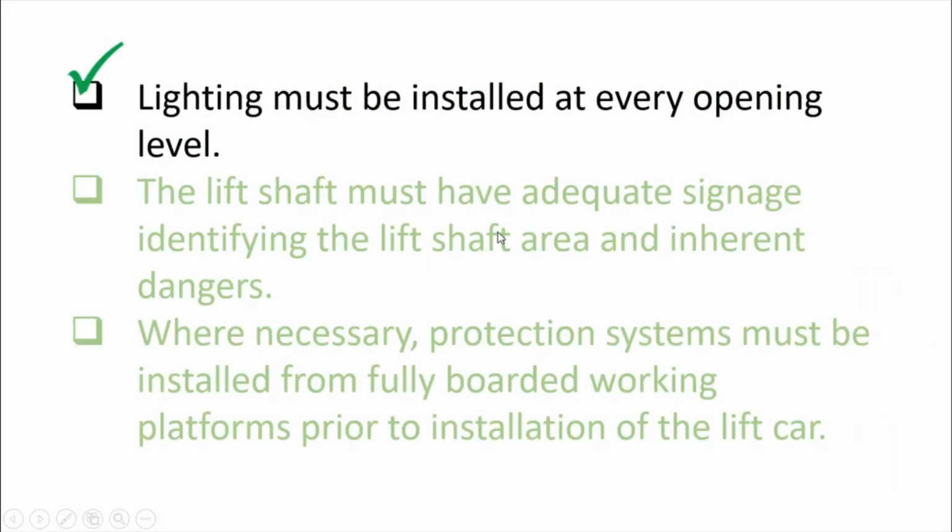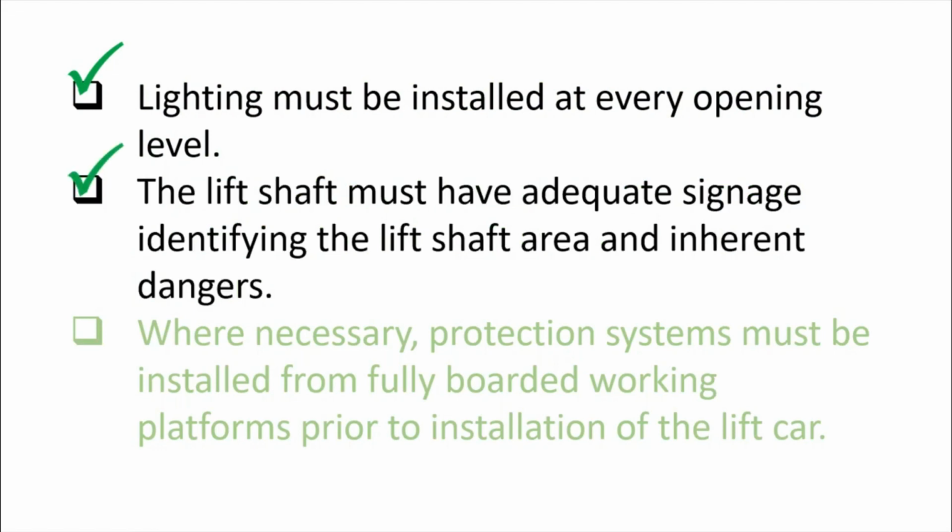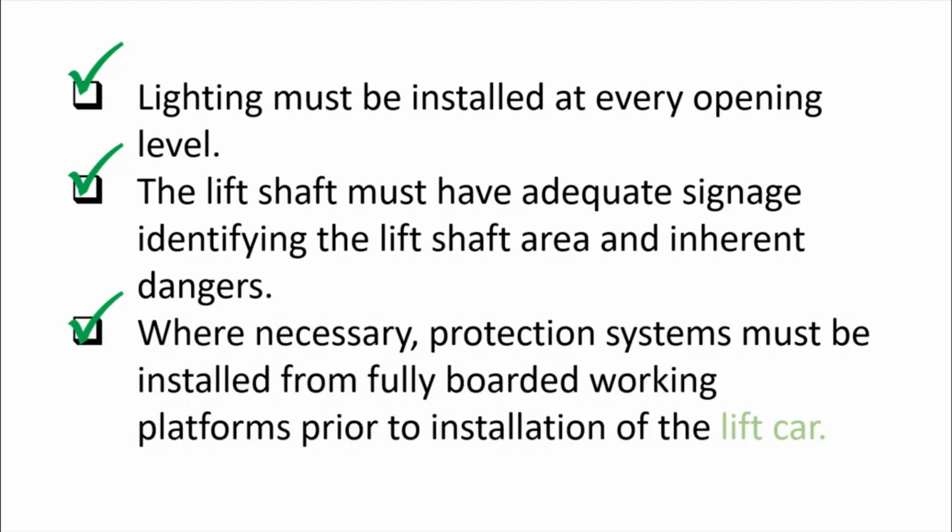Lighting must be installed at every opening level. The lift shaft must have adequate signage identifying the lift shaft area and inherent dangers. Where necessary, a protection system must be installed from fully boarded working platforms prior to installation of the lift car.